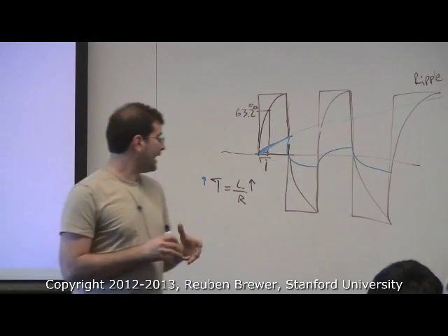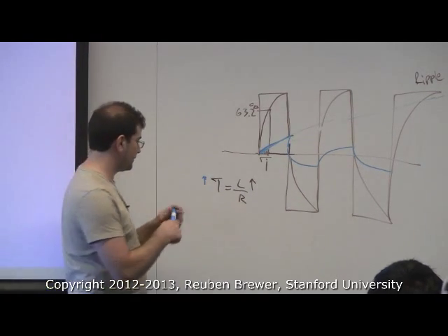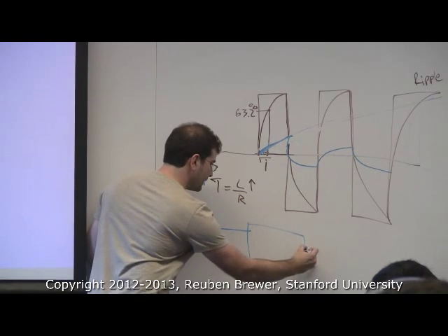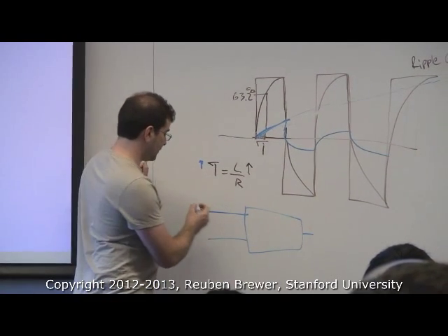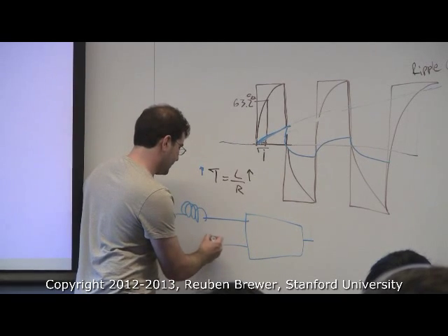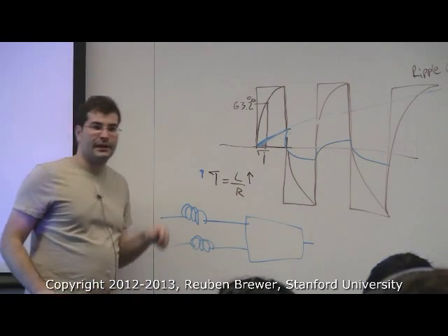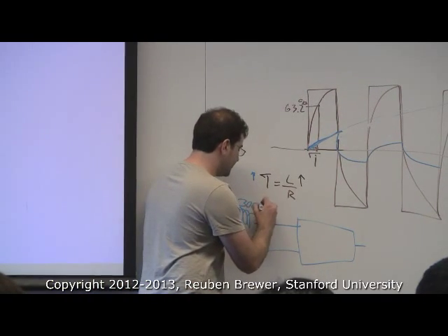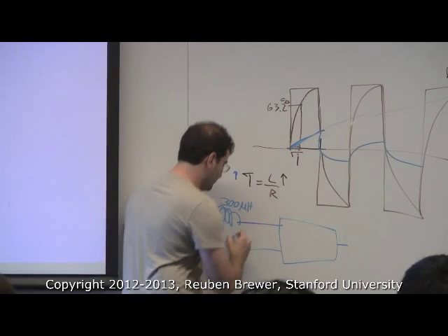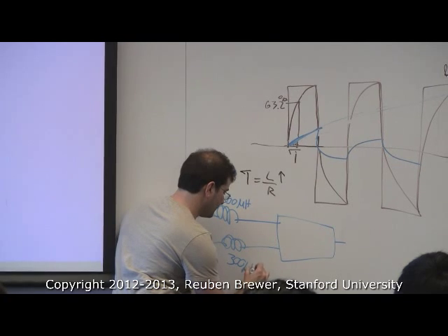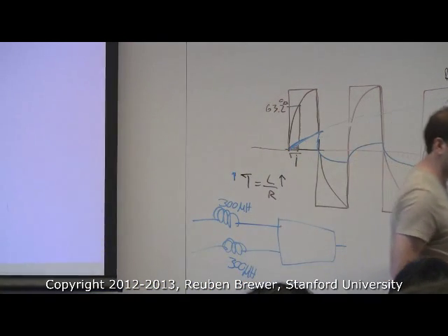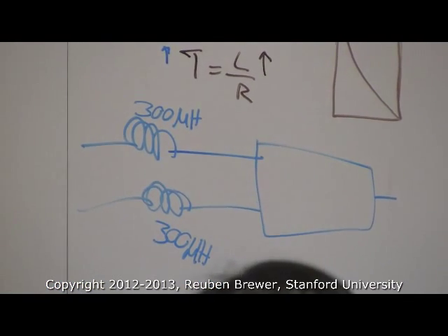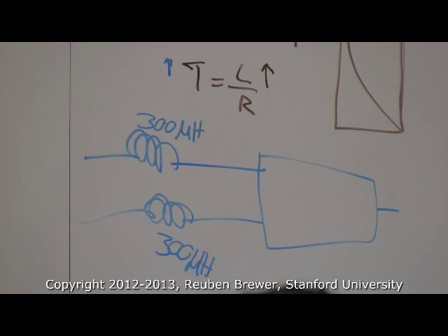So what do we do? We add inductance to the motor in series. So if this is our motor here, and that's the shaft, and these are the leads, you literally solder in a coil of wire here and a coil of wire here. And on average, between RE30s, 40s, 50s, and 10s, etc., they recommended, and I have seen it work pretty well, about 300 microhenries each. If you're going to scribble anything in terms of lectures this quarter, I might scribble today's lectures, because this is stuff that will save you hours of, oh shit, why isn't my motor working?